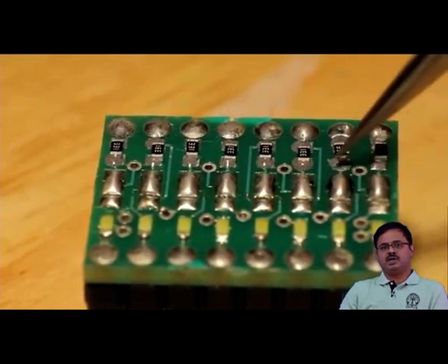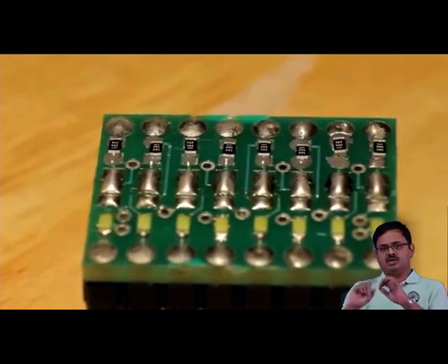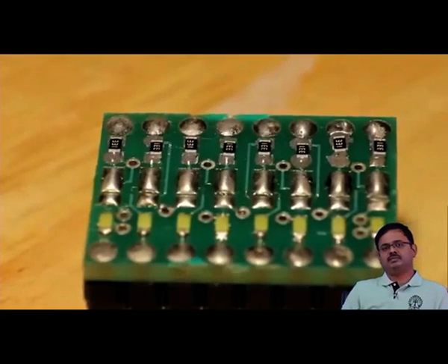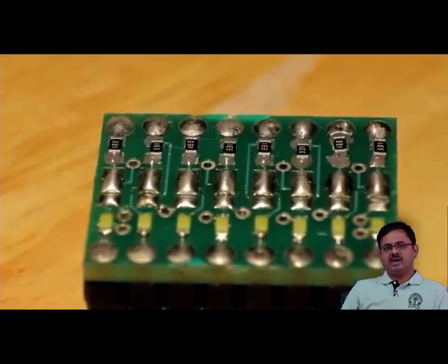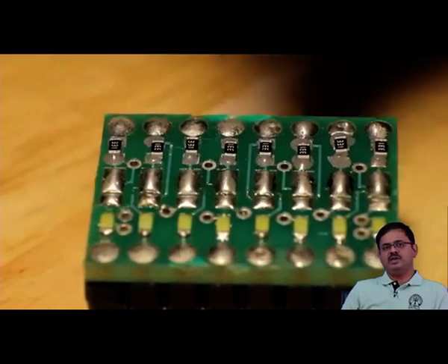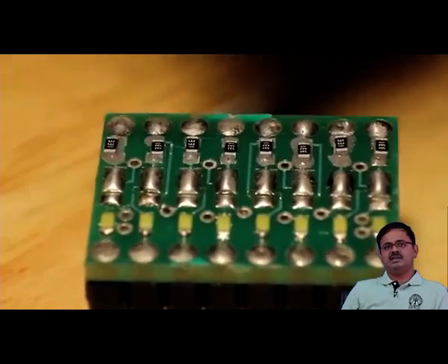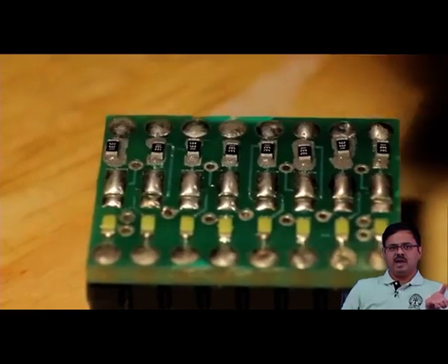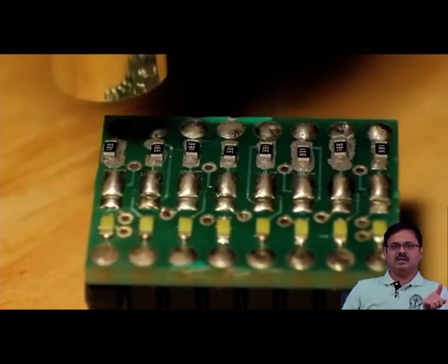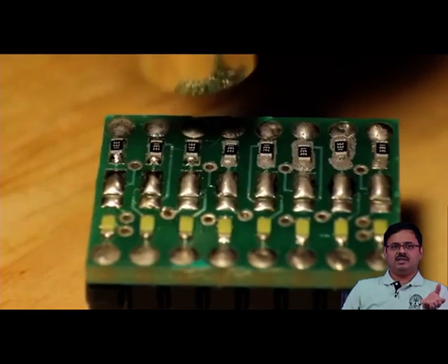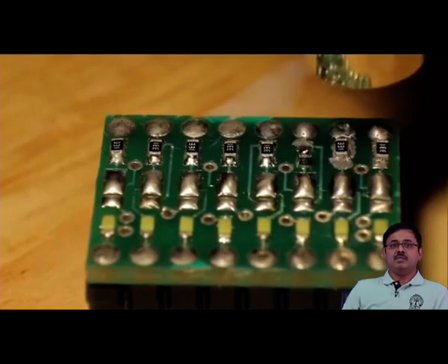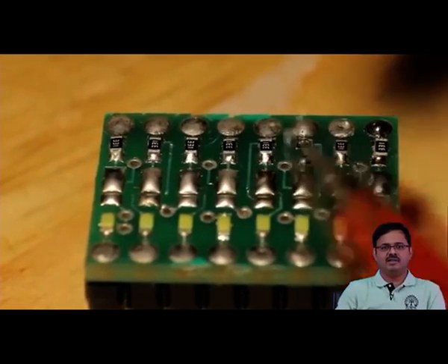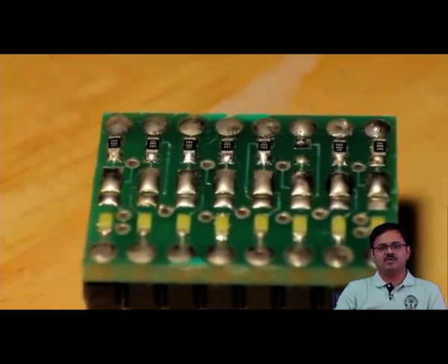Next he is going to heat up, so that the solder on both sides does melt and wets the joints. See what happens here. Here it is not a reflow oven. What the user is doing is, he has taken, I think, a hair dryer or some kind of a hand blower, heat gun. And you see the way they are all aligning, but this one, the fourth one, suddenly lifted off, right. The one that he removed, that was an example of tombstoning.